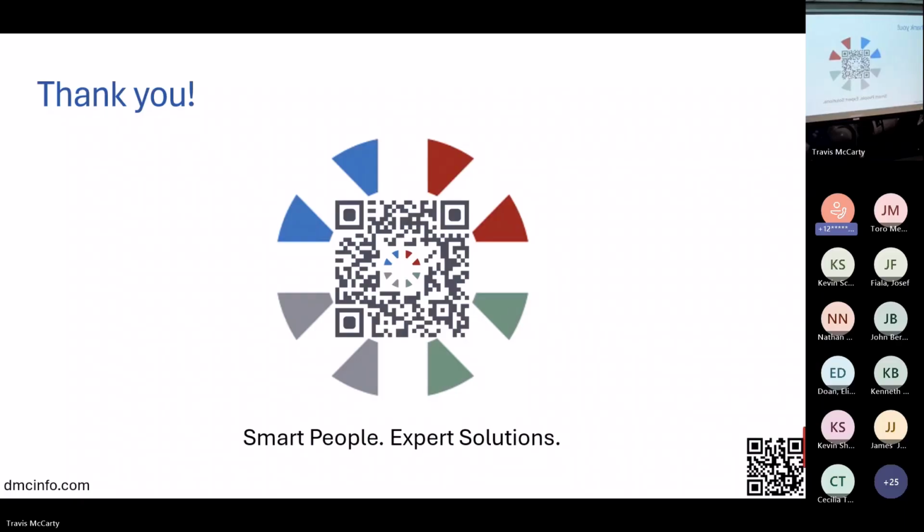And that's why I put a banner at the top of all of our designs, see safety critical considerations. As an example, we say to the developers, you have to indicate on your block diagram which parts of the code are safety critical. So you put a red decoration. For a VI that contains any of that, there has to be a red border around it, things like that. So lots of different considerations. I wasn't aware of that, so I need to.